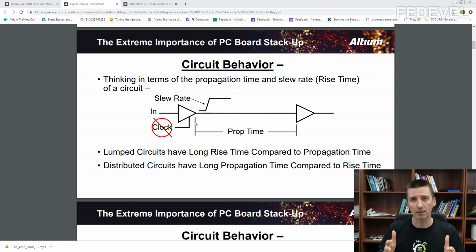So even if you are designing boards which are running, I don't know, for example, on a microcontroller, you still may need to take special care of the signals, because it depends how these signals of the microcontroller are going to change. If they are changing very quickly, you still can see problems like crosstalk or reflections on your board.